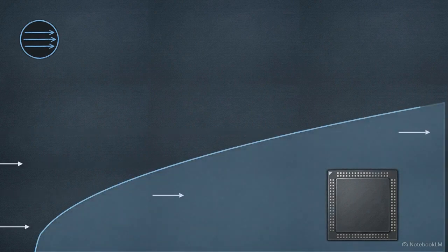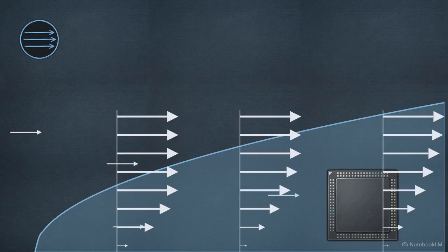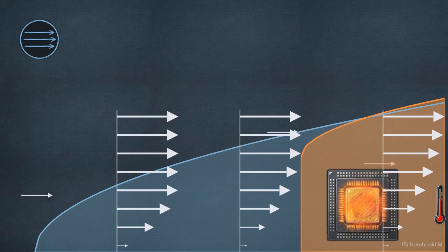When designing thermal management for electronics, you often deal with air flowing across a cold, inactive substrate before it ever reaches the component you actually need to cool. From the exact physical edge where the air meets the board, friction takes hold. A velocity boundary layer begins forming immediately, slowing and thickening the air down as it moves downstream.